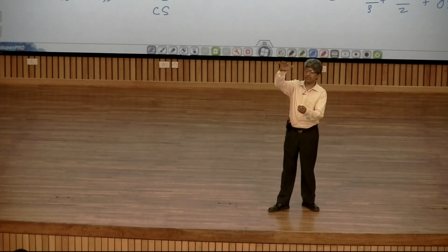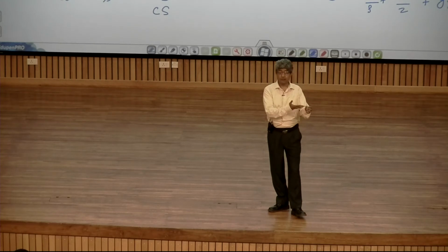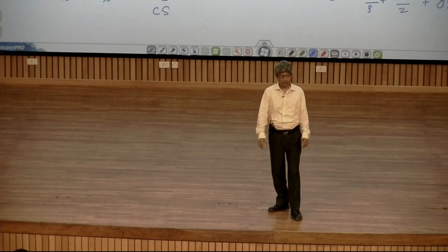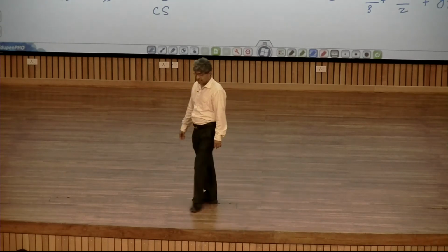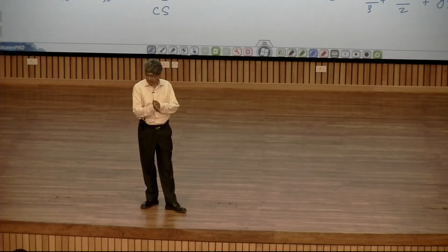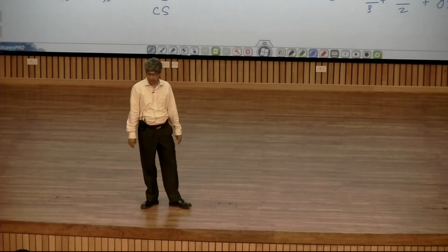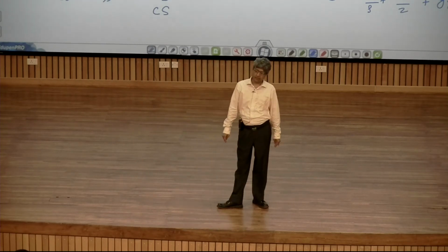So, elsewhere fluid is moving, at the wall it is stationary, and you have a velocity gradient set up. This gradient permits internal friction to come into picture. It's almost like one solid surface sliding on another, giving rise to internal dissipation within the medium.